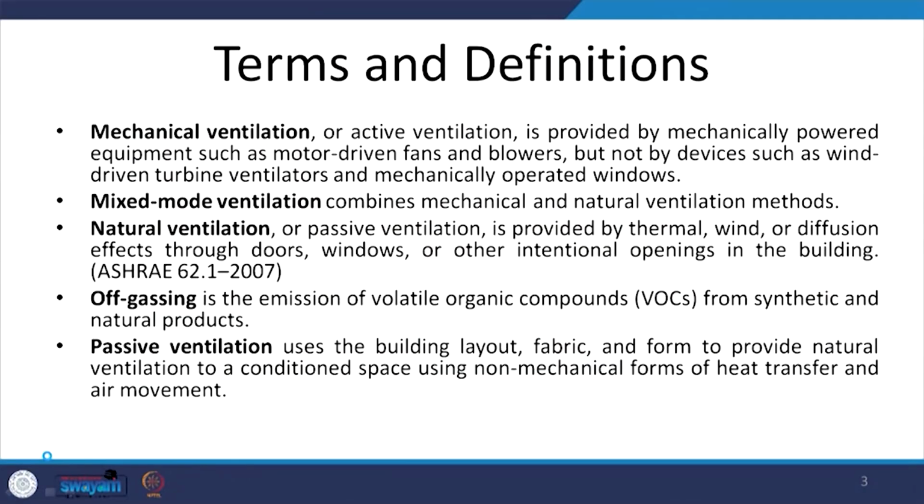Next, we have mechanical ventilation or active ventilation. It is the amount of air movement exchange which is provided by using mechanically powered equipment, for example, fans, blowers, or more of such mechanically driven equipment, but it does not include ventilation provided by using devices such as wind ribbon turbine ventilators or mechanically operated windows, because these are only operating the openings but not really supplying the air inside.